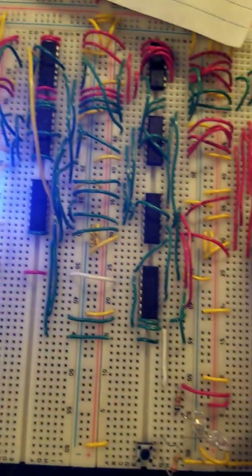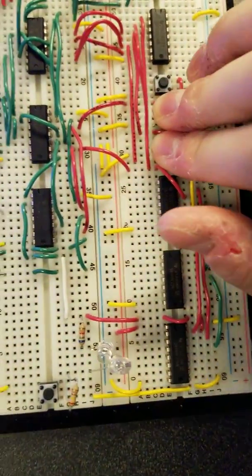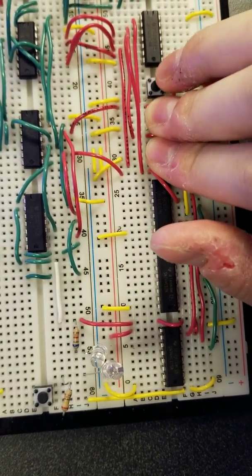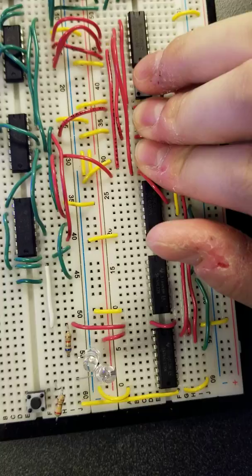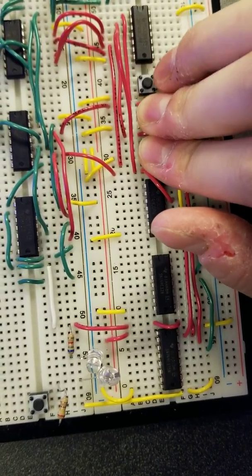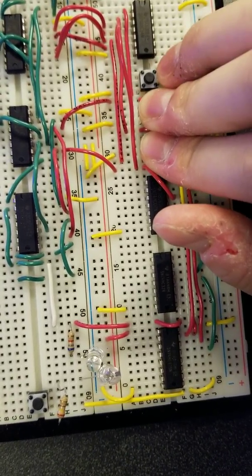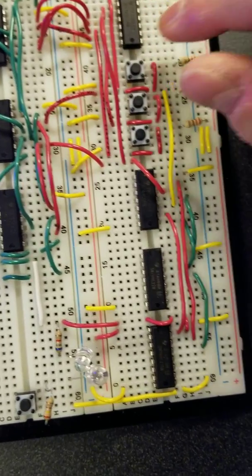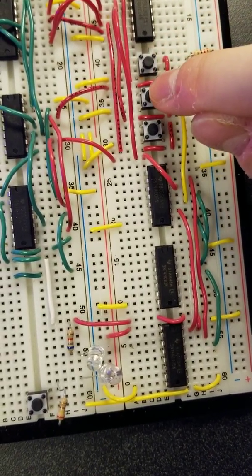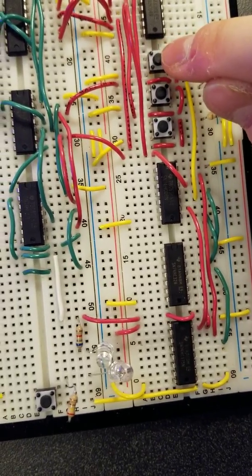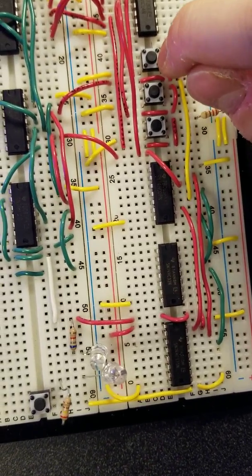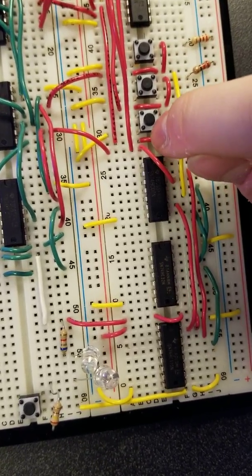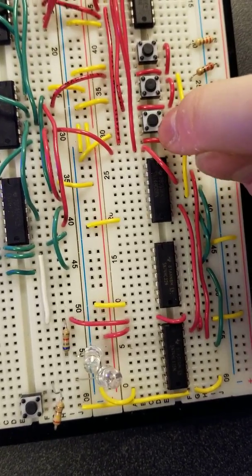Now, here's where this factor FSM comes into play. So, we track an intersection by checking what photodiodes 1 and 2 are inputting, which is this button right here. Just as a refresher, this is P12, P34, P56. So this is the ANDed version of photodiodes 1 and 2, the ANDed version of photodiodes 3 and 4, and the ANDed version of photodiodes 5 and 6.